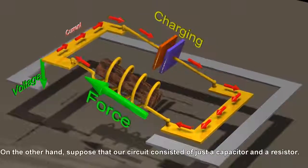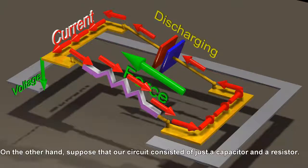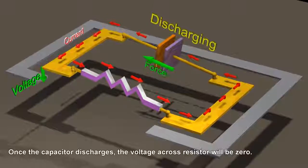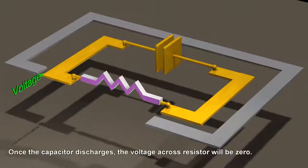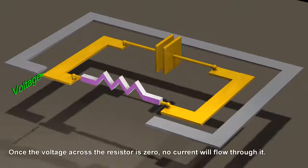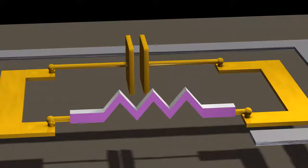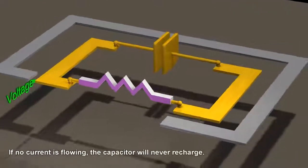On the other hand, suppose that our circuit consisted of just a capacitor and a resistor. Once the capacitor discharges, the voltage across the resistor will be zero. Once the voltage across the resistor is zero, no current will flow through it. If no current is flowing, the capacitor will never recharge.